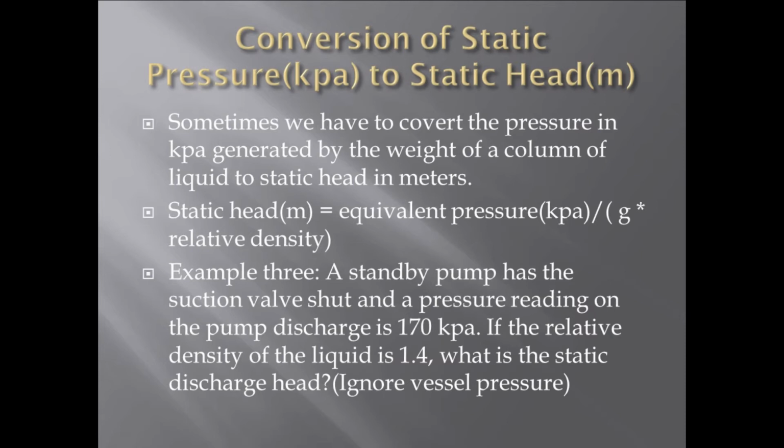Example 3. A standby pump has the suction valve shut and a pressure reading on the pump discharge is 170 kPa. If the relative density of the liquid is 1.4, what is the static discharge head? Ignore vessel pressure.